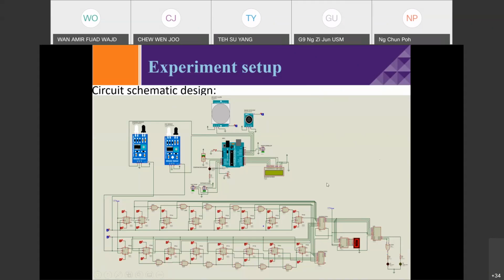So here we have the 8-bit counters. There are two 8-bit counters, one for the entrance and one for the exit. Both of these entrance and exit counters will be cascaded to the 8-bit subtractor. We cascaded it by connecting the exit counter's bar Q output to the second binary number input of the adder, so they become the first complement.